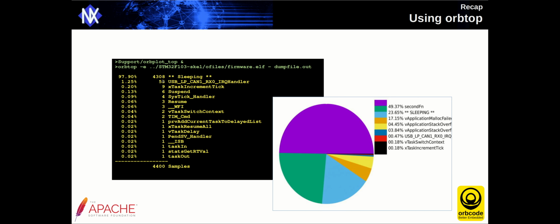By reconstructing those program counter samples and referencing them against the ELF that makes up the executable, you can turn that back into individual line numbers or files or functions to be able to see what the CPU is doing. And then there's some nice eye candy to be able to plot out graphs and so forth, lots of bits and pieces that you can do of that nature.